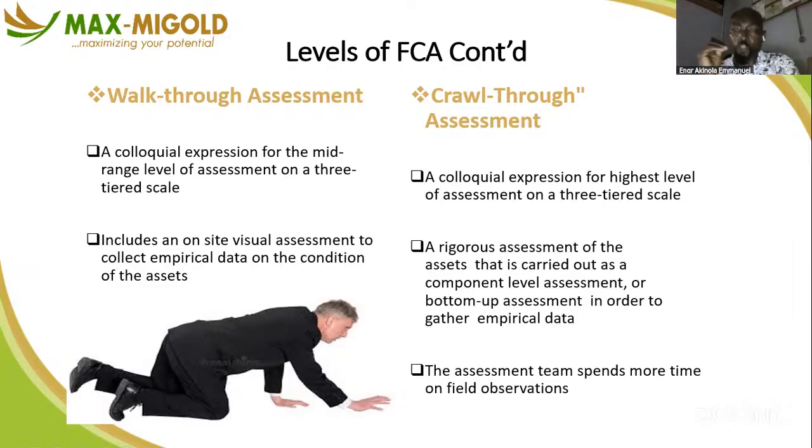But the crawl-through, which is the top tier scale, is a rigorous assessment of the asset that is carried out as a component level assessment. You look at every component within the entire facility, or you refer to it as a bottom-up assessment, in order to gather empirical data. The assessment team spends more time on the field of observation because they have to look at every component of the building.